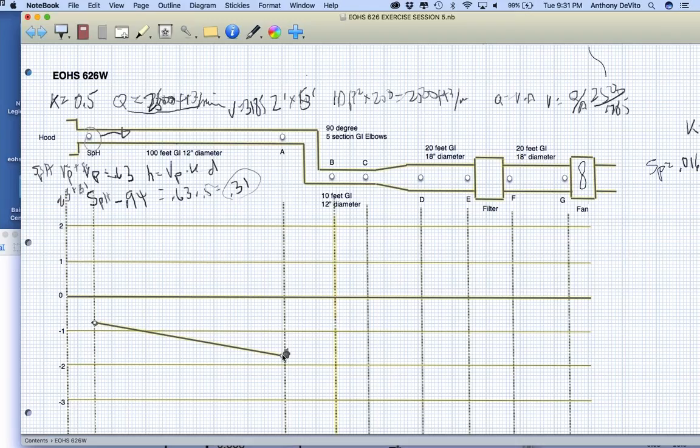Right. Okay, so now we have more resistance. We're going to lose energy to 2 turns. A lot of times you're going to run into turns in ductwork because you're working in a plant, there are going to be obstructions. You got to go around lighting, you got to go around posts, support posts and stuff like that. So in this case, I'm going to say it's 2 quick turns. I'm going to ignore that length of ductwork in between. I'm just going to say it's 2 90-degree turns.